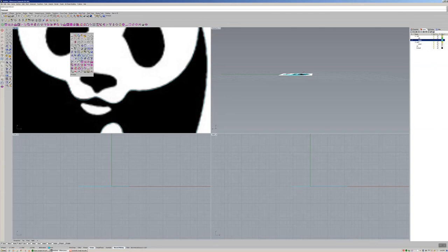Okay, so I'm going to use my middle mouse button and choose interpolate points, but where was it over here? What do I do here? It's the second one down from the top. Yeah, but what mouse button do I click and what do I do to select this? Left click, hold, go over the command, inner bullet point, let it go. And now, how do you know it's on? Because it has the plus. It's saying, at the command line, start of curve. Okay, got it. The command line's telling you that we're starting with the first point, okay?